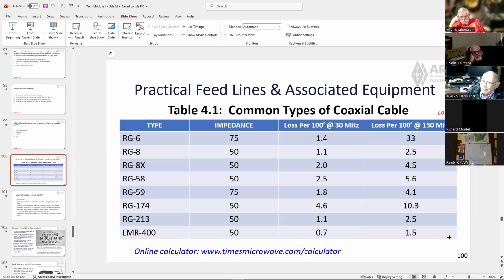But if you have 200 feet of RG58, which is 1/4 inch diameter, and you run 200 feet of it out to an antenna, you're going to have so much loss in the coax that you're almost better off putting a rubber duck on a handheld than running that much RG58 coax out to a better antenna, because the antenna will give you some gain, there's no doubt, but how much did you lose in the coax? You have to look at the overall gains and losses.